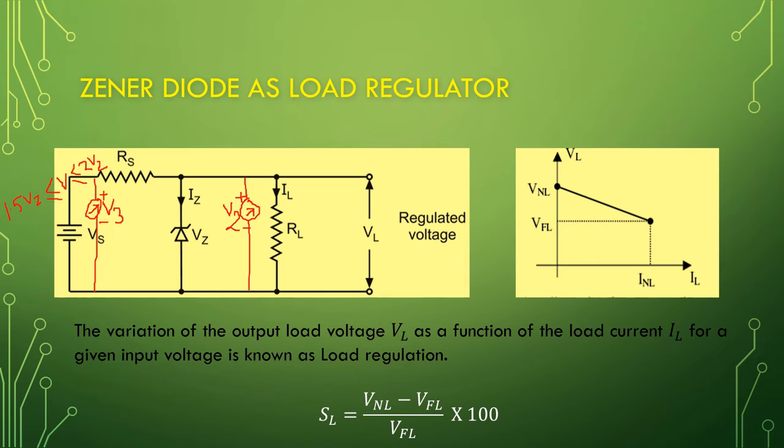Okay. So in this range, we can fix the input voltage, which is much higher than the value of Vz. Right. In this condition, first of all, disconnect RL, that means load resistance. This makes IL equal to 0.